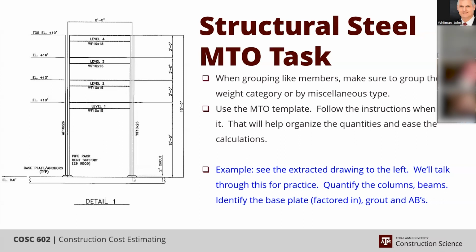Yeah, this one here is fairly straightforward, so it doesn't include, and again, this goes back to, we're not trying to get too deep in the weeds. We're just trying to get everybody comfortable with the general concepts. So I didn't provide a full set of specs with all of this. So it's all going to be ASTM base specifications for it, and also assume that the grout is non-shrink. So there's no real rotational moments or anything to worry about using epoxy grout in this case. But that's a valid question, valid statement.